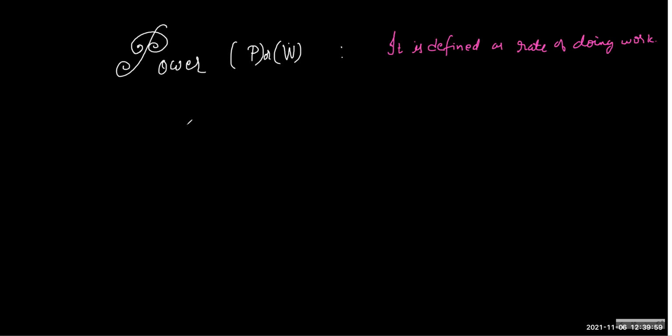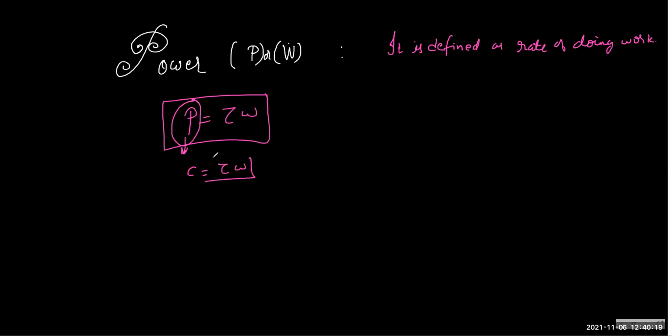Now if you look at the engine power, the ability of the engine to burn the fuel is fixed. So this power is fixed. We cannot burn all the fuel at once. We can burn fuel only at a certain rate. So this is a constant quantity, and then we derive the other two things. To climb the steepest part, the engine cannot produce more power than this, because the car comes with fixed power called BHP, brake horsepower. The BHP rating will tell you at what rate I can burn the fuel in the best case scenario.